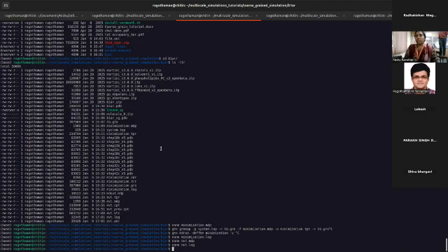This NVT step will be generating 5 files. The first one is the CPT file, which is the time point file. This can be used to restart the simulation from that step. Mostly for the NVT step, this will not be useful. It will be useful for MD, where you cannot run continuously for a long time. You can stop it here and then resume it. After analyzing, if the results are fine, you can stop there, or you can restart. So these are useful for continuation from a time stamp.